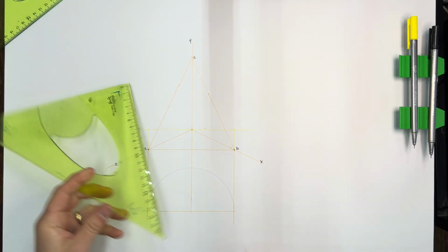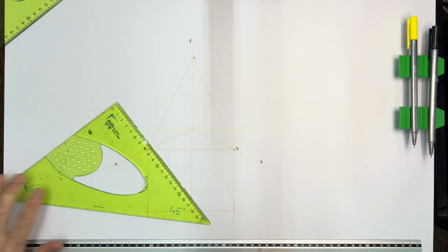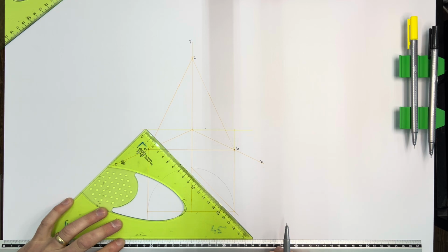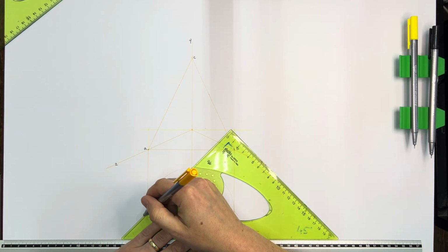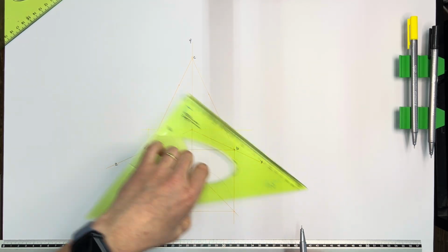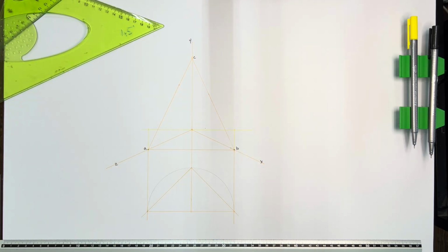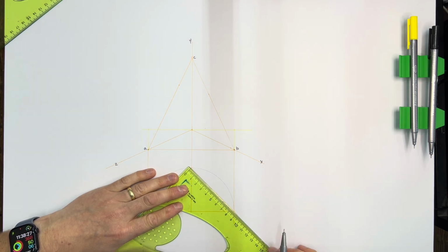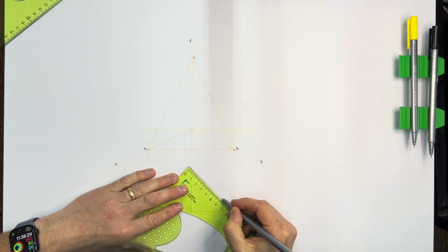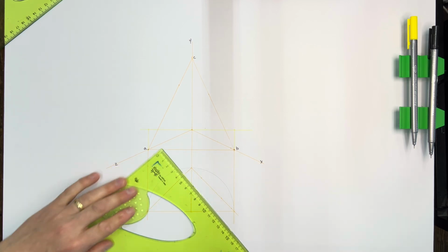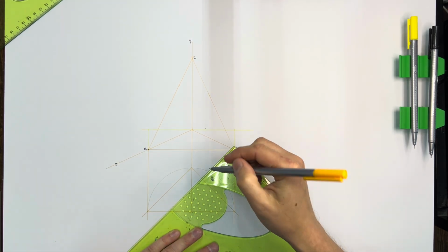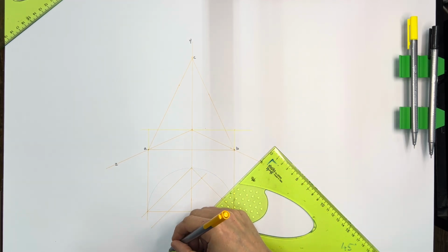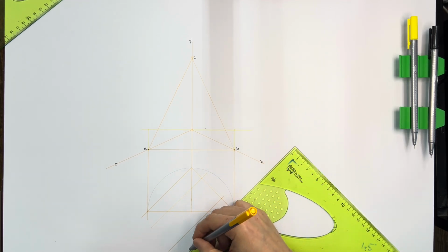Now, what that gives me is a right angle triangle, which shows me the orientation of my plan. So I know that because the y-axis is in the center, the angle set is 45 degrees. So that's the orientation angle of my plan. The dimensions are 20, 40, and 20. So 20, 40, 20. Immediately, I'm just bringing down construction lines from those points. That's going to help me draw this drawing.